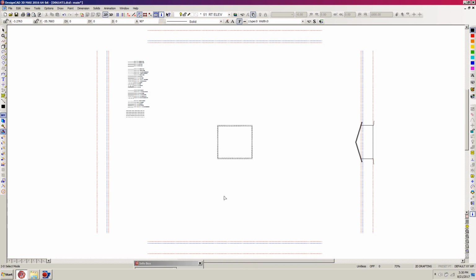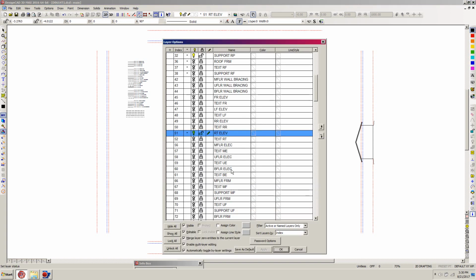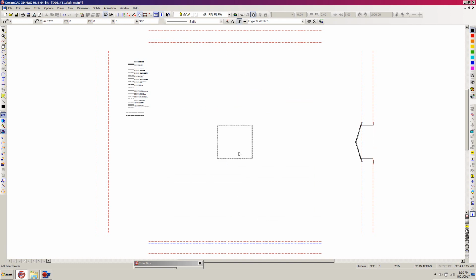And what I want to do now is the front elevation. The quick and easy way to do that is first I need to go to Layers, L for Layers, and that'll be in layer 45, so I'm going to make that my current active layer, and then click OK. And I'm just going to draw a line, hit V, and I'm going up to orthogonal mode up here, and right click into this corner and bringing it on down to our floor line. Hit K and hit Enter.